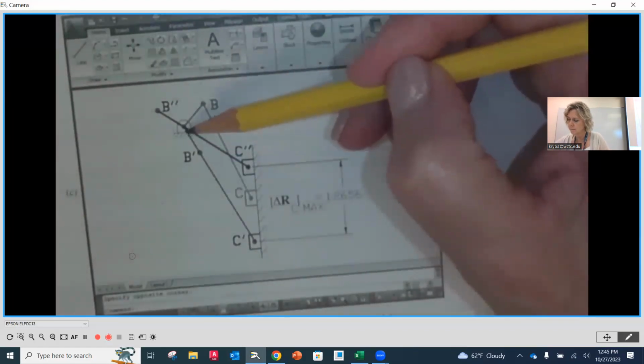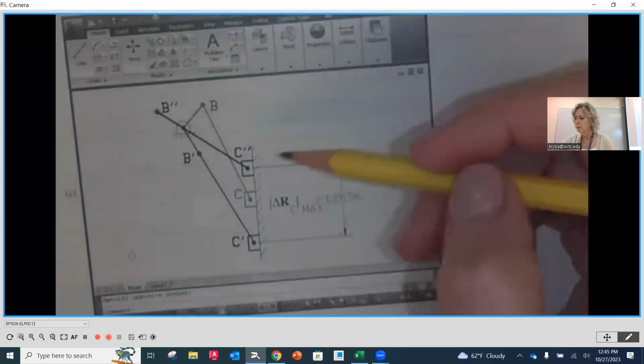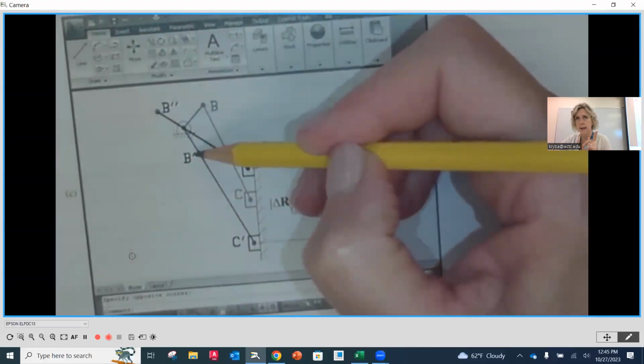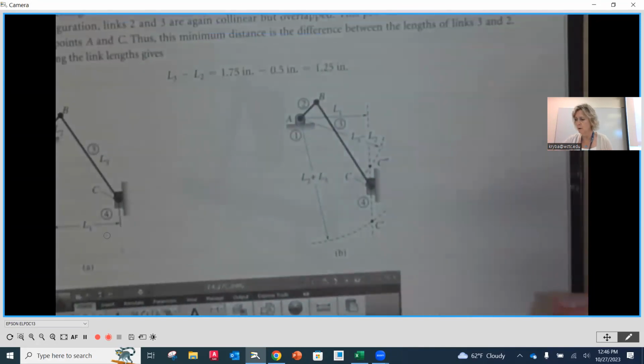We see B in line all the way with C. So this is like in its furthest position down. And we strike that arc of link number 2, its length, plus link number 3, its length. And that's what we see up here in the construction.